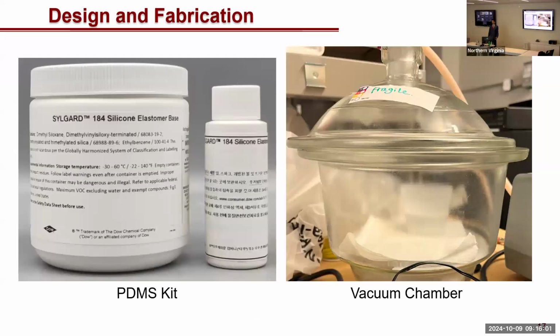So this microfluidic chip is made out of material called polydimethylsiloxane, or PDMS for short. We use PDMS because it is flexible and it's clear. It's also very valuable because you're able to cure it. So you can pour it into a mold to produce very small features. And